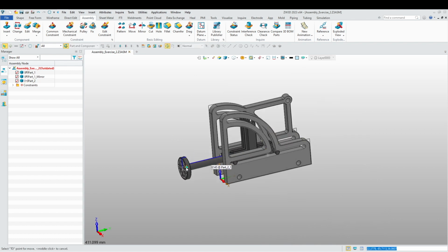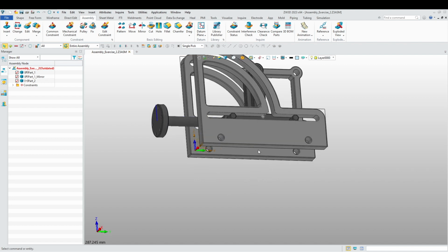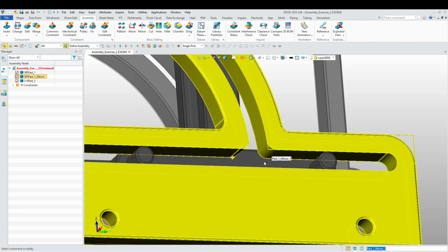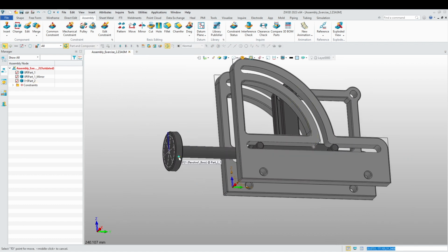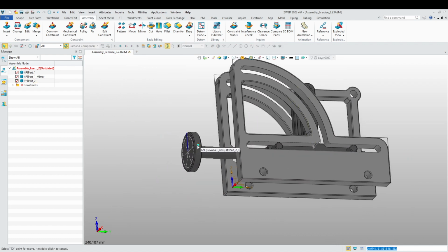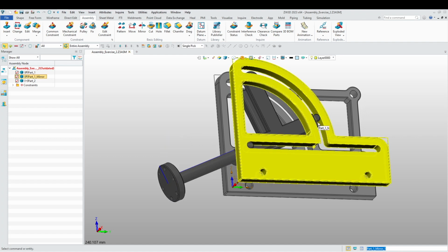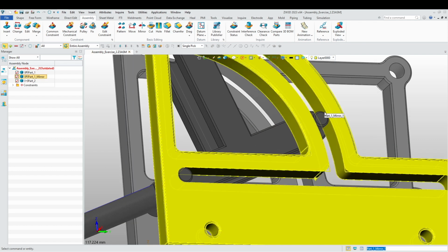Alright, okay, good. So now, as you can see, we have our alignments. Now, if you remember, when I did this part over here, I removed these edges and created one whole face. It was precisely so that this part over here can slide up this face once I did a tangency from that face of this cylinder to the face of this part.